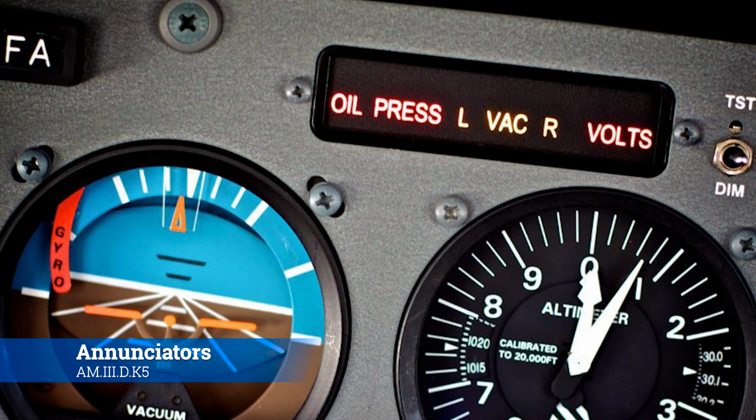Now, this is probably what's ended up happening on this one. It's not in test mode, because you can see the tester right there on the right. Usually you can flip it up and all those lights will come on, to make sure that none of the lamps are burnt out. It's probably that the power's turned on, but the engine's not running yet, so it's giving you all those indications because the engine's not turning. If the engine's not turning, you're not going to have oil pressure, vacuum, or voltage. So that's probably what's happening here.